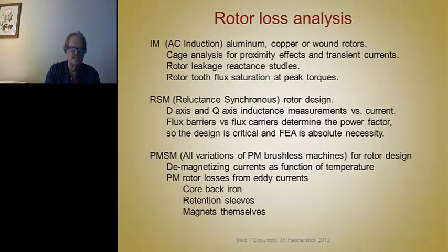and it's very important in induction machines that are inverter fed, as I've said before, to balance the cross-sectional area of the rotor to have acceptable current densities in the bars, and yet not take up so much space that we don't have enough cross-section to carry the flux for peak torques. Because to get peak torques out of an induction machine, we've got to have high magnetizing currents, because it's still a shorted turn. We can't adjust the current like we can in a stator. We can reduce or increase the current that it takes to produce torque by changing the number of turns.